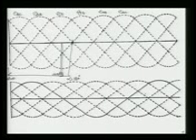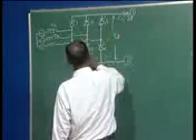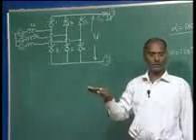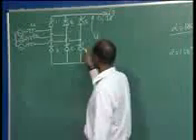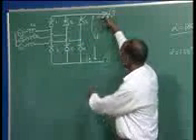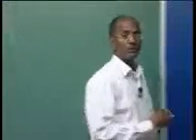Now we give a firing pulse at this point, and valve 3 is going to be fired. Once valve 3 is fired, what will be the output voltage? We are assuming valves 1 and 2 are conducting and 3 is getting the pulse. So with 2 there, EC was there, and now here we get EB. So the voltage EB minus EC will appear. Now you can see where EBC is in this graph. You can find this EBC here, starting at this point.